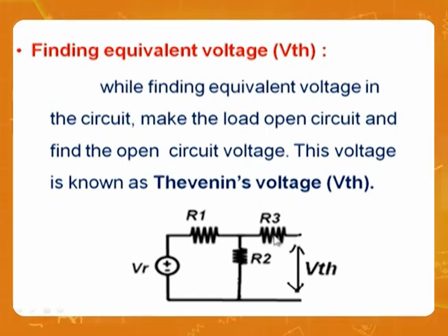When there is no current in this branch, what is V Thevenin here? It is as good as here. Why is there no current in this? Because it is open circuited. So V Thevenin is nothing but the open circuit voltage. In any series branch with no current, across this, the direct answer is V by (R1 plus R2) into R2, which is V Thevenin.